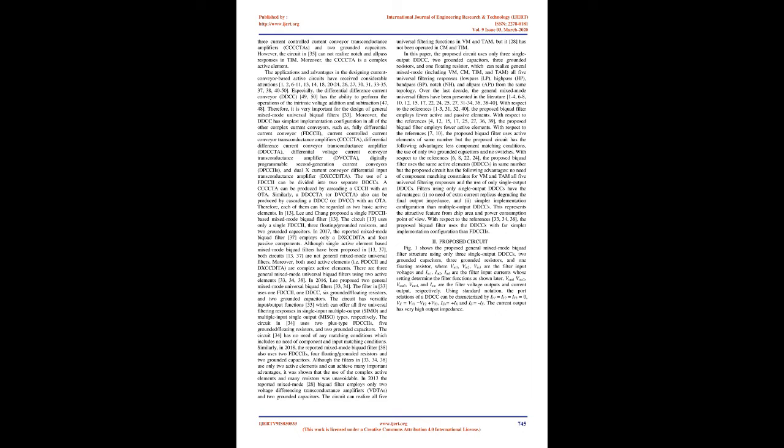In 2013, it has been shown that the mixed-mode universal biquad filter [27] needs to use 4 multiple output current-controlled current conveyors, MOCCCIIs, and 2 grounded capacitors. However, it needs component matching conditions for realizing VM notch, all-pass responses and TAM low-pass, notch, all-pass responses. In 2016,